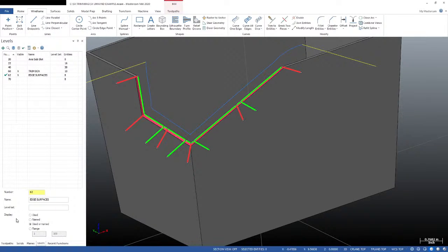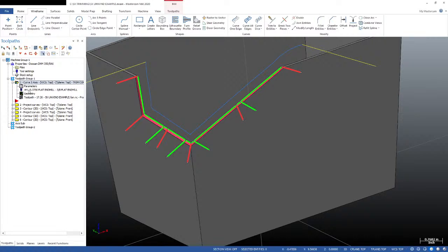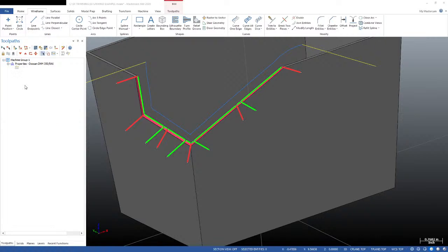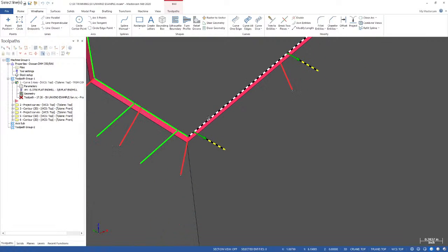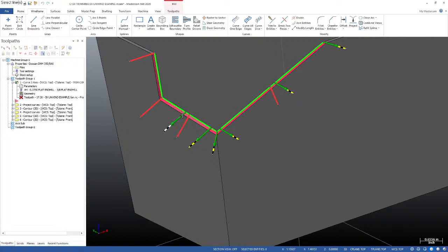We'll save that. What I'm going to do now is go into my curve 5-axis toolpath. I'm going to go to my tool axis control lines, and I'm going to click on clear. So I'm going to remove those lines, and I'll select new ones. So now I'm going to choose that line, this line, this line, and this line. And then I'll choose this guy and this guy. Can't forget that one.